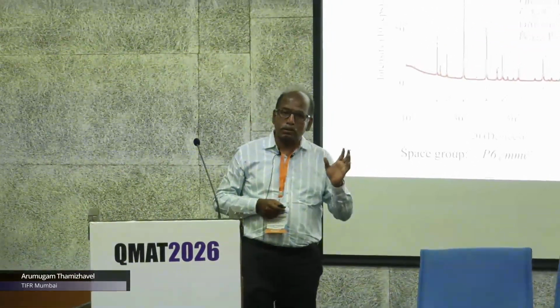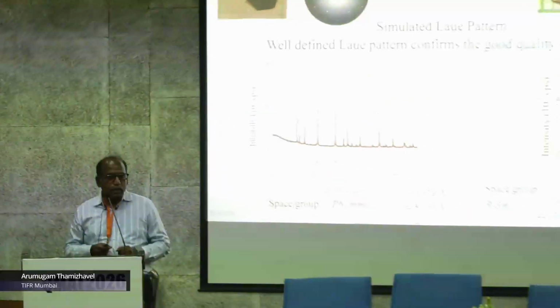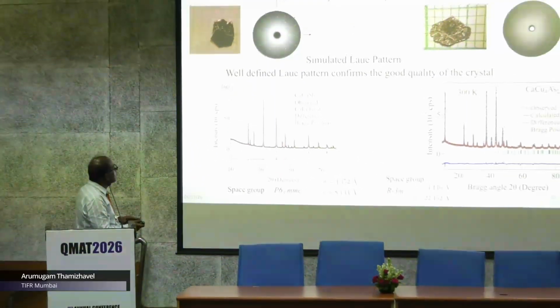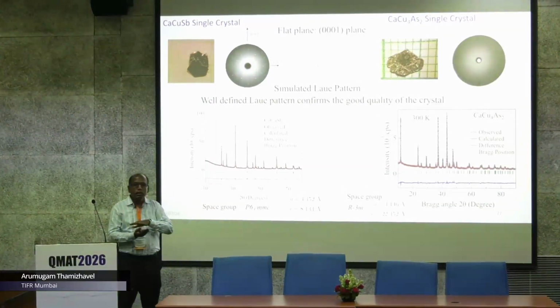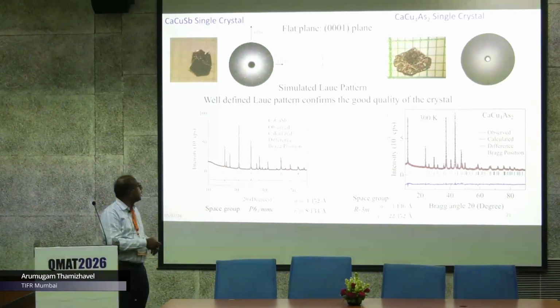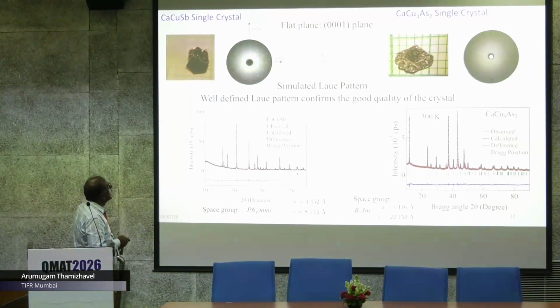And this is how the grown crystal looks. So after removing the flux, we get pure single crystals of these materials. And as a rule of thumb, the largest crystallographic direction has the slowest growth front. These are platelet-like single crystals, and you get this kind of hexagonal type crystals.